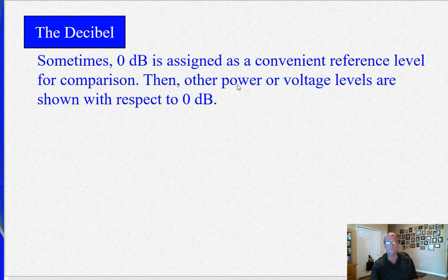Okay, so a little table here. 0 dB is usually just a gain of 1. So it's a buffer. So output voltage is the same as input voltage in terms of voltage gain. For power gain, it's very rare that you'll have a power gain of 0 dB. Usually you would have 0 dB voltage gain, but some substantial power gain. Example of this would be a voltage follower, emitter follower, common collector amplifier, which we looked at a couple chapters ago, right? They have almost 0 dB, or AV gain of 1, but the power gain is substantial. Power gain is basically what your beta is. So you could have a power gain of 100, all right, which turns out to be 20 dB, okay?